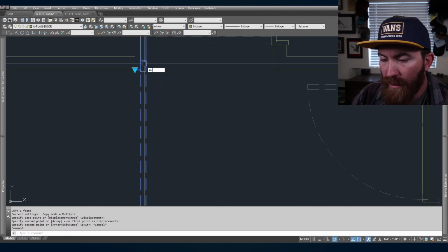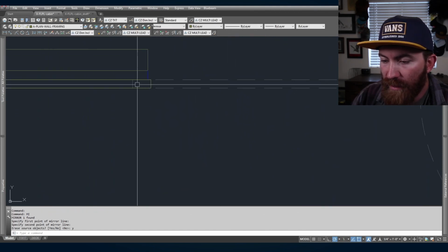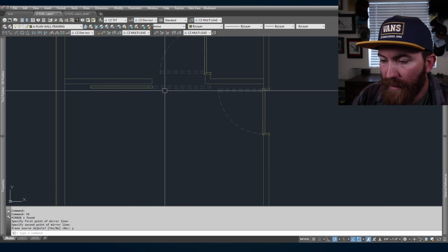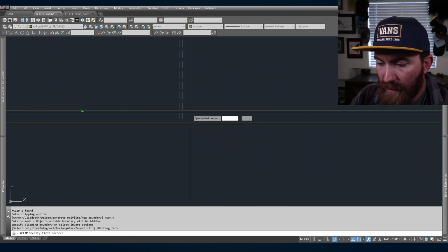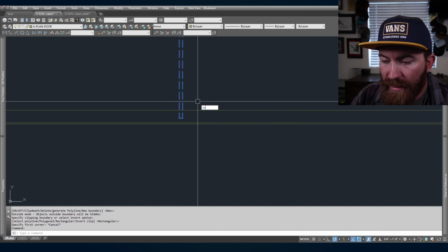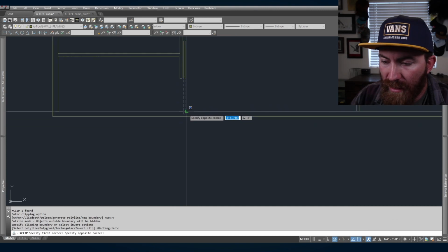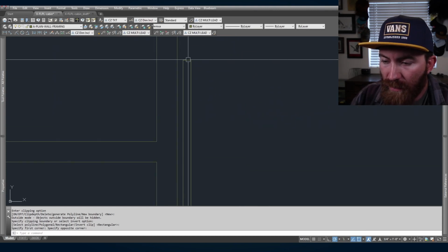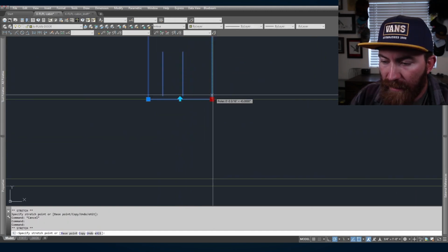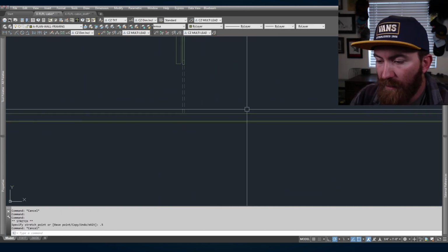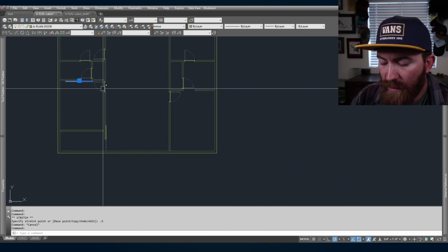And click there. We're gonna hit mirror it at a 45, delete original, boom. You can see how that 42-inch covers that opening. Okay. I'm just gonna allow this one. I'm gonna do an XClip on it, which is you select it, you type in XC, and then you type new boundary, rectangular. So I just hit space each time. And now, all the way to here. So what it does is it clips anything outside of that box. So you see that? I'm gonna hit 0.5, because that'll be my wall finish. And booyah shakaza.